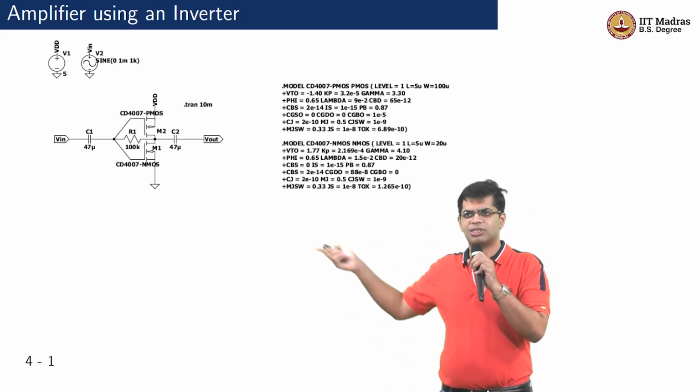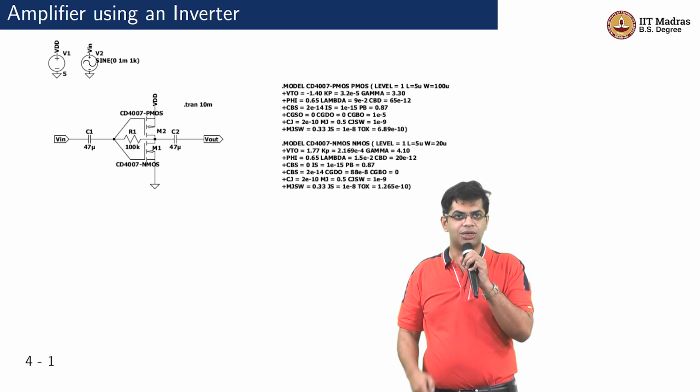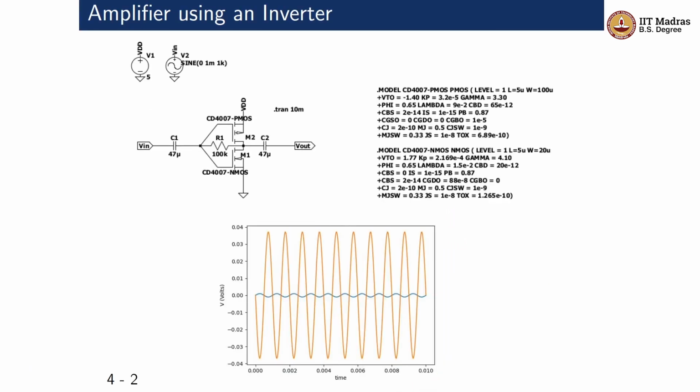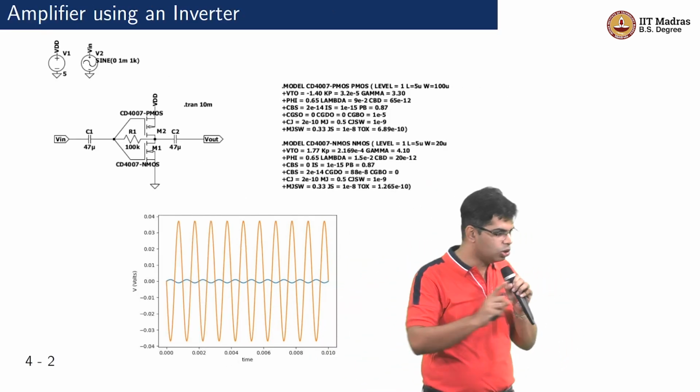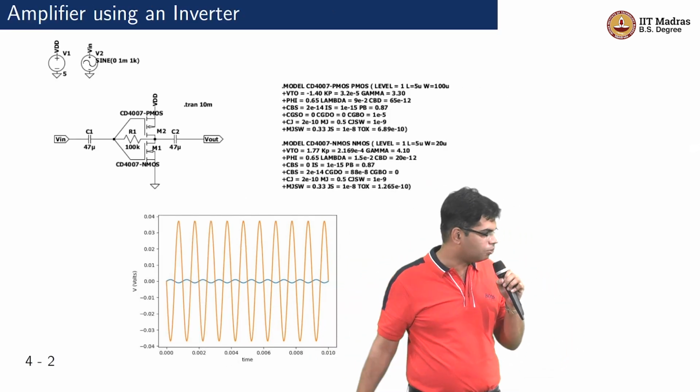So this is just a SPICE simulation. I have some parameters. If you bias it as an amplifier, you see that you have decent gain, right? My input is quite small, output is quite large. You get an inverting gain of about minus 50 using this. So this is the first thing. We will show you all of these as we have wired up on the board, right?